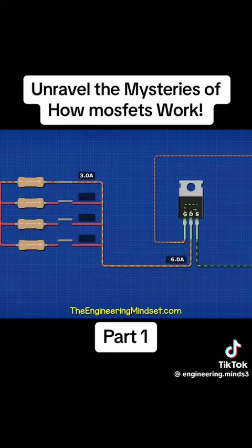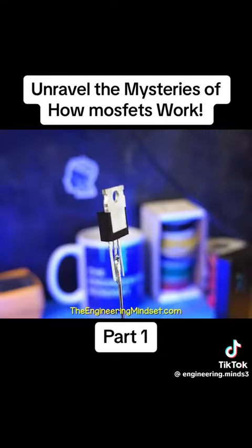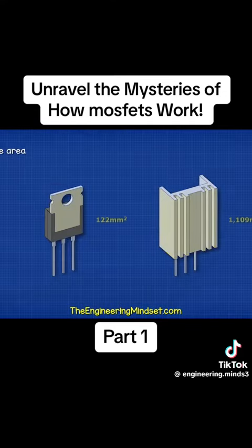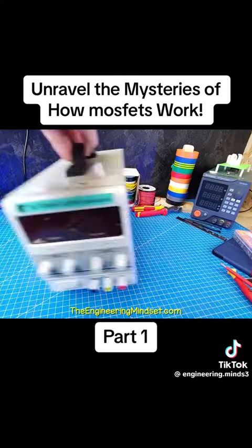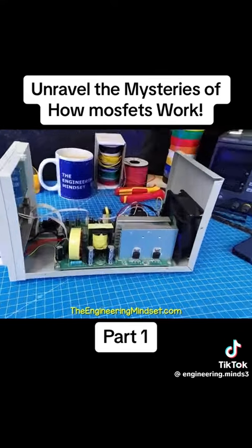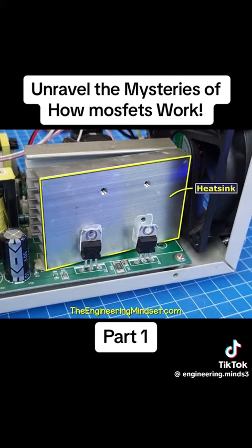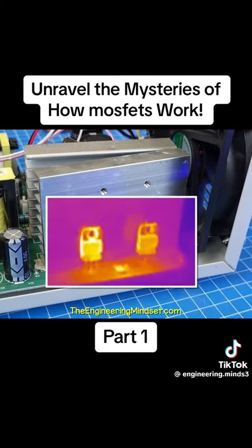Some electrical loads have a high current, which causes the MOSFET to heat up. So we attach a heatsink, which increases the surface area with the air and helps to cool it down. For example, this DC power supply uses MOSFETs. The MOSFETs are attached to some very large heatsinks. Without them, they quickly rise in temperature.